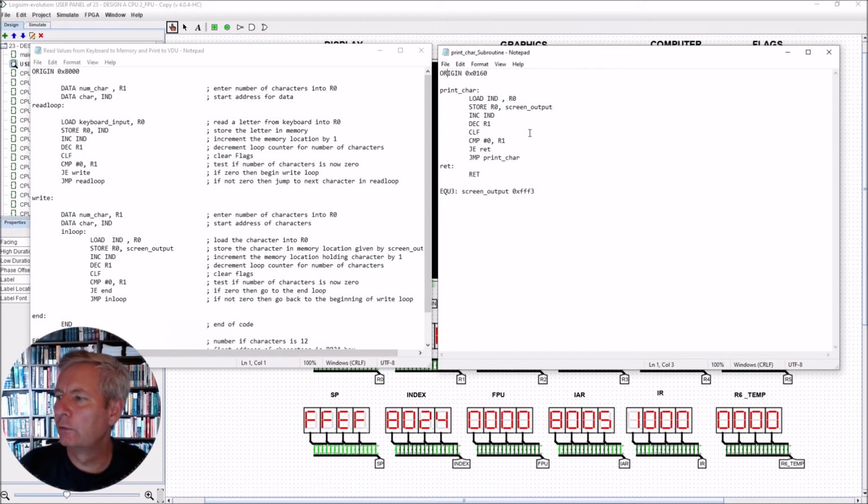We're going to have to then run through the assembly language and then take a copy of the output from the assembled code and then put it into the ROM at the correct position. So I'll just go ahead and do this now, and you can also go ahead and do it.